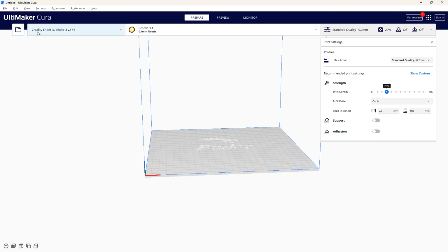Now that I have the right printer, I'm going to just check to see if the nozzle size is correct. Just about every printer that comes starts with a 0.4 millimeter nozzle. If you've made changes to your printer or your printer has something of another size, you can make that change here. Like a very common one is 0.6, just to print models a little faster and maybe bigger, stronger models, okay? Of course, you can go down the other way too. I'm going to just leave that alone. And PLA is pretty common for everybody that's starting out.